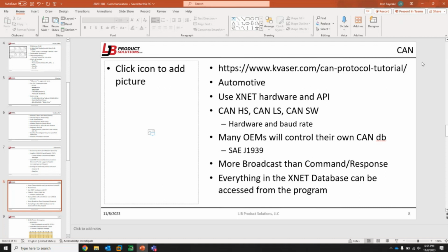Because we have, at Stratic, the Electrak HD actuators that communicate over CAN. It just says that your ID is built up of something. So there's a certain manufacturing code within those 11 bits or 29 bits. There's a manufacturing code, and then there's like a source. So it's this manufacturer, it's an engine. And now I know that these bytes are the engine RPM and these bytes are the engine temperature, that kind of stuff. So if you're building any implement for it, you can request that you have a certain ID value, and then that's yours, and here's how your data is packaged.